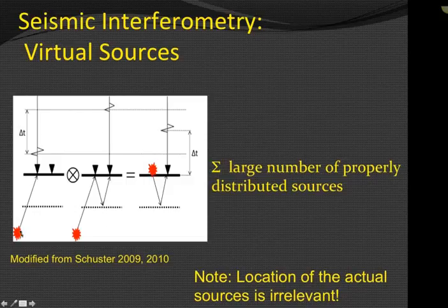The illustration is meant to show that if you take the record of a subsurface source recorded at a seismograph at a position here, and you correlate that record with the energy that would come up from the surface and be bounced from the surface as a multiple back down and reflected off a target interface back to another geophone at some distance here, the correlation of this record with this record here and here gives you this record, which is effectively, at least in terms of time and spectral content, the signals you would get if the actual source was really located at this virtual source position. You have actually turned a subsurface source into a virtual source at the surface, and now we can process this the same way we'd do if we're doing an exploration survey using vibroseis or explosions.